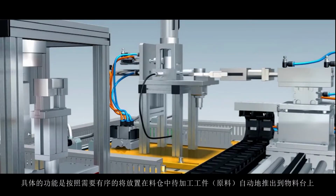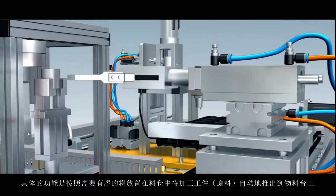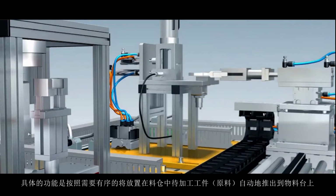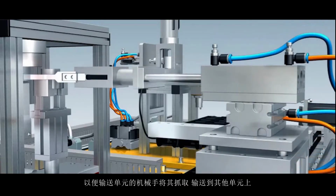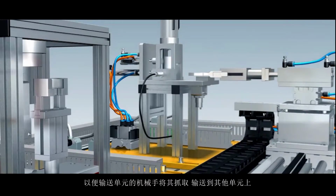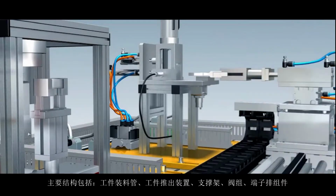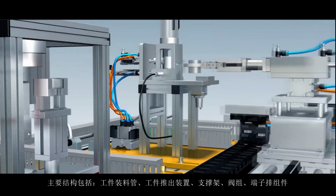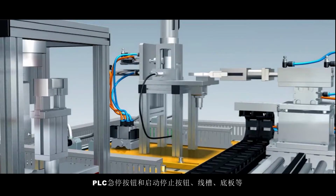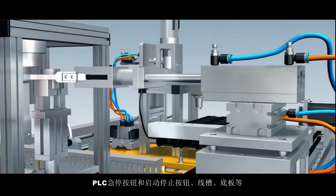The specific function is to automatically push the processed parts and raw materials placed in the hopper to the material table, so that the manipulator of the transport unit will grab it and transfer it to another unit. The main structure includes workpiece loading pipe, workpiece release device, support frame, valve group, and terminal assembly, PLC, emergency stop button and start button, line slot, bottom plate, and so on.